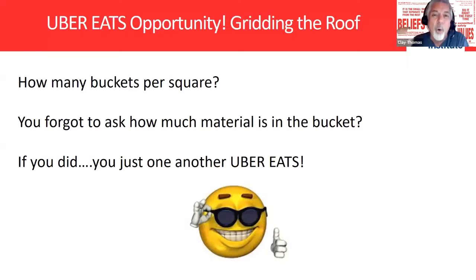So again, if there's anything I want you to walk away with from this conversation today, we did dry film last time, we did wet film, and we talked about wet film thickness, is to know that a lot of these products, especially the 2-part products that you get, are not true 5 gallons when you mix them. So if you think you're using 5 gallons, you're not. So whether you're ordering, whether you're loading the roof, you bring a crane out, you load the roof, you think they're all 5-gallon buckets, you've got 20 buckets, you got 100 gallons? No. You might, if you've got top coat, you might have 20, 30% less than that.